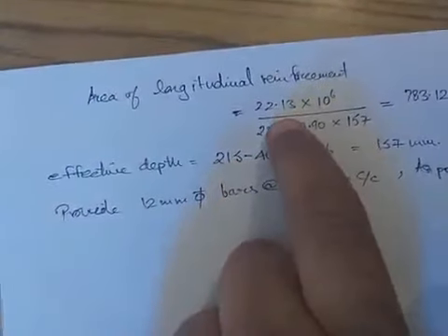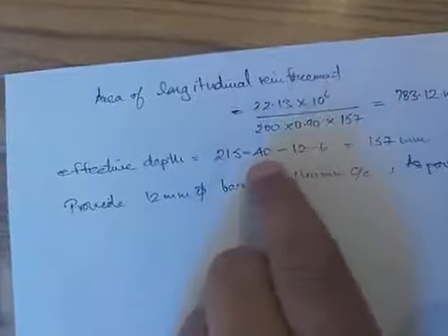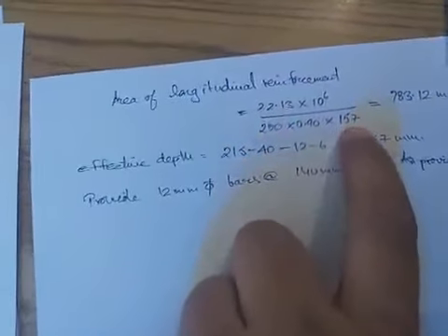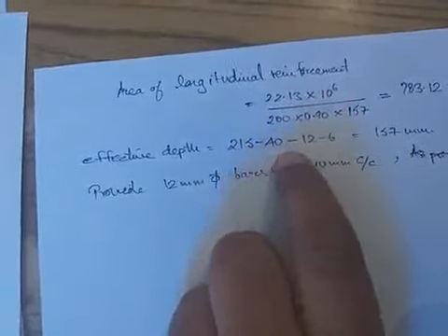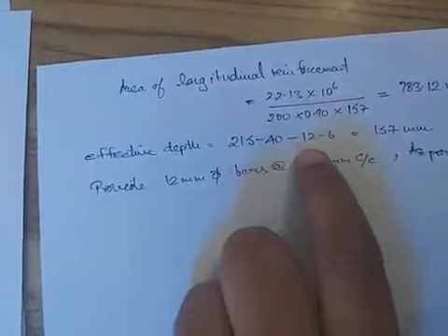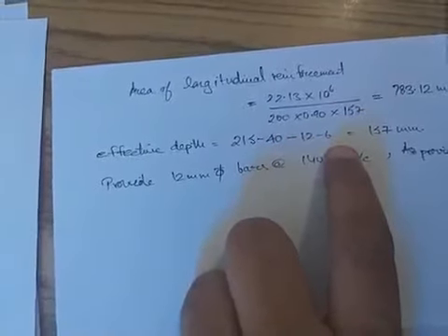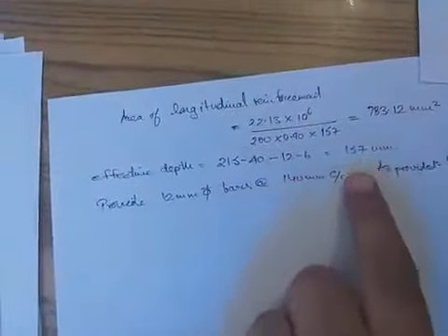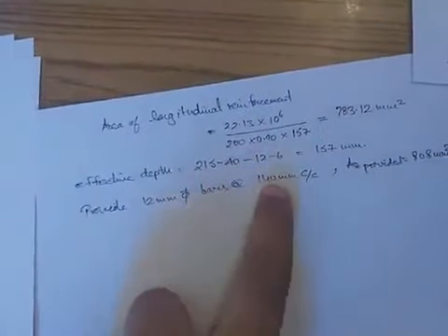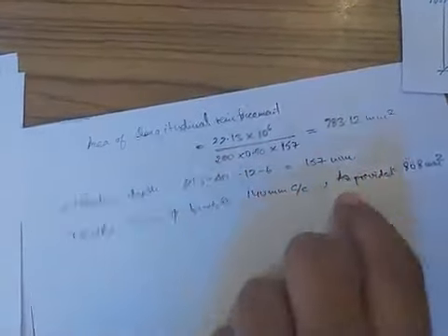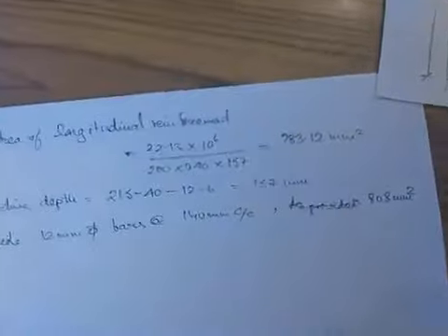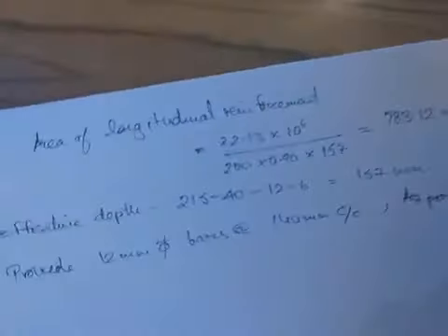The critical bending moment there will be 22.13, and hence you can provide the steel. The effective depth in this case will be 215 minus the cover minus one bar of the steel minus half the bar of the steel in the other direction. So it is 157 mm. You can provide 12 mm bars at 150 mm center to center, and the Ast provided is 808 mm square. So this covers one part of the design which we have, the design of the deck slab.